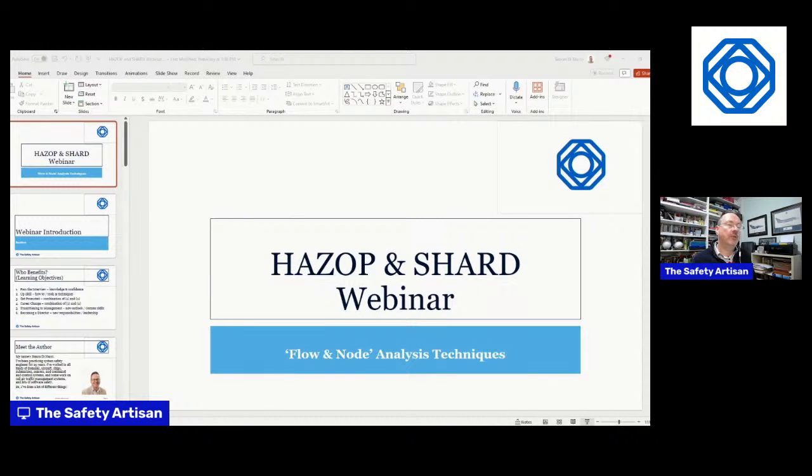So that's very important. And then finally, you should do a safety audit after a few months of operation, just to see whether the HAZOP results were accurate, whether we've overestimated some problem or maybe we've missed something. So a piece of follow-up work is really good.